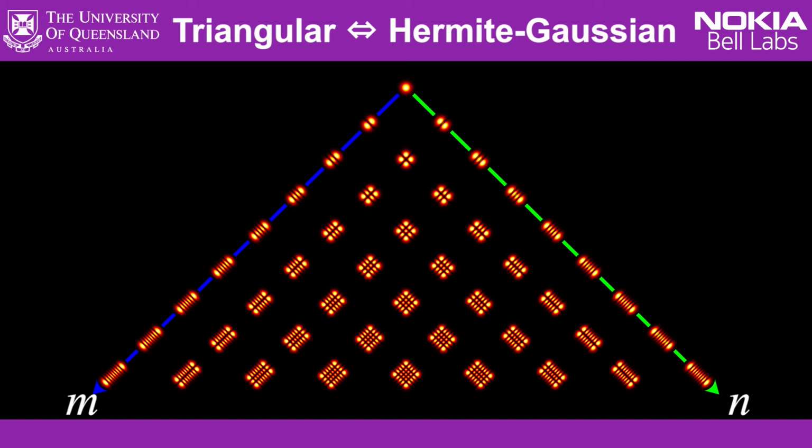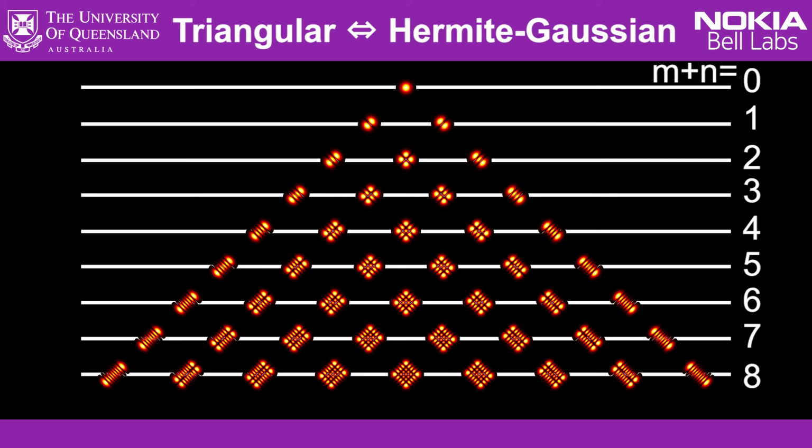But it's also an excellent mapping in the context of graded index multimode fiber, because each Hermite-Gaussian mode consists of a superposition of near-degenerate fiber eigenmodes. So ideally, each HG mode consists of a superposition of fiber modes with almost exactly the same propagation constant and group delay. So modes within these mode groups couple heavily in a multimode fiber anyway, almost immediately.